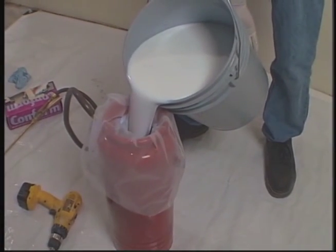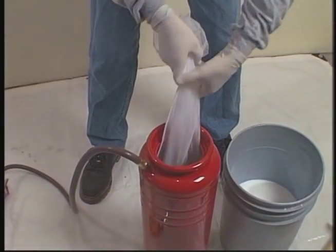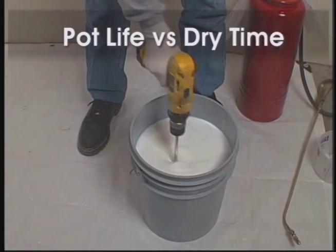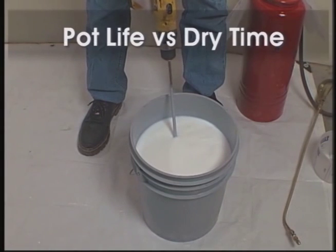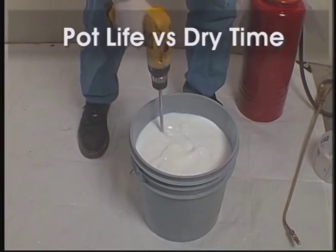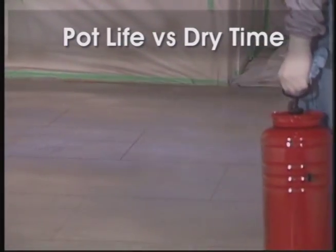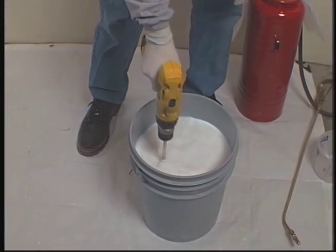Once the components have been properly mixed and blended, pass the material through a fine mesh filter to remove particulate, which may clog spray equipment or leave contaminants in the finish. Mix only the amount of material that can be applied within the product's pot life. Pot life refers to the amount of time the blended product can be kept in a container before it begins to harden or lose its chemical reactivity. Dry time refers to the time it takes for the product to set up after application. Know the blended product's pot life and dry time. Mix the proper amount of material for the specified coverage.